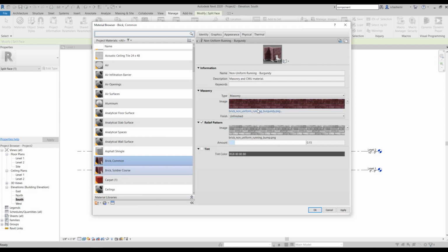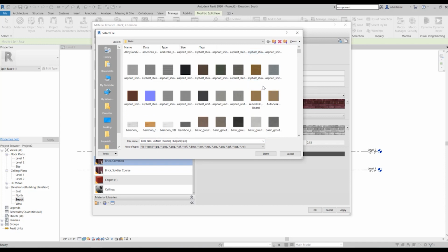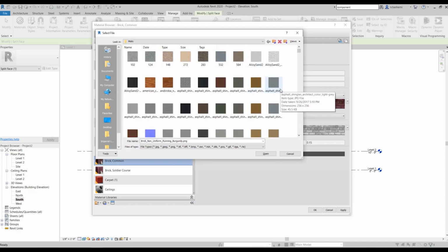So right below the image, on the material image, is a hyperlink. If you click on this hyperlink, it actually takes you to the material folder in your computer, okay? You can switch the view to thumbnail. Okay, you can see the materials here, or we sometimes call them maps. Okay, so we have many patterns here.